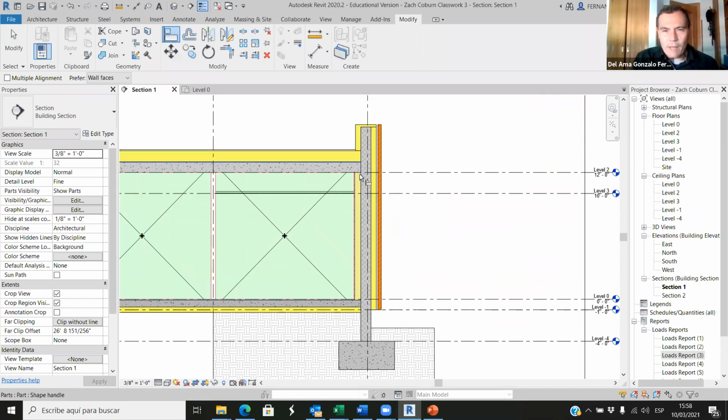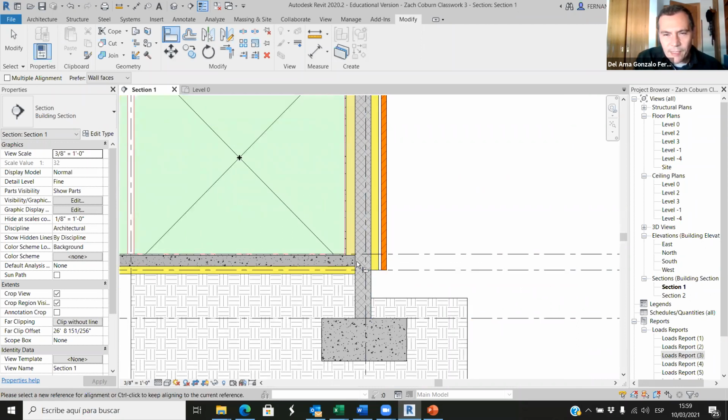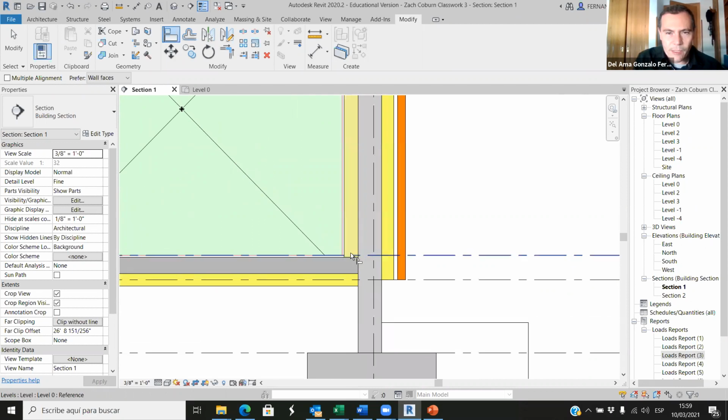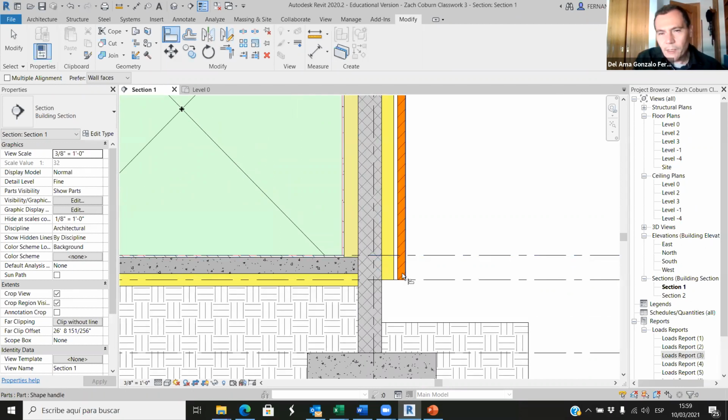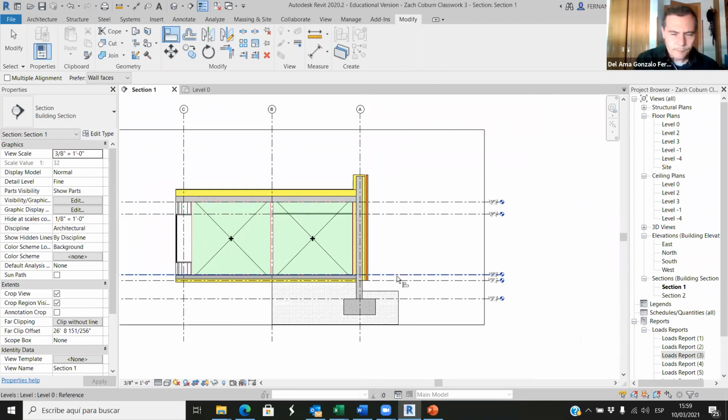And we know that we have different materials. We understand what the structural materials are. The grayish is always the structure, then the thermal insulation, and then this one is the finish. So there's a lot of information here. And here we have fixed, we know the order. First we have the footing, then we start building this, then we place the slab. Well, first we place the rigid insulation on the floor, and then we place the slab over the rigid insulation. Then we start with the cellulose here. We know that we need something to hold this weight there. So there's a lot of information here.